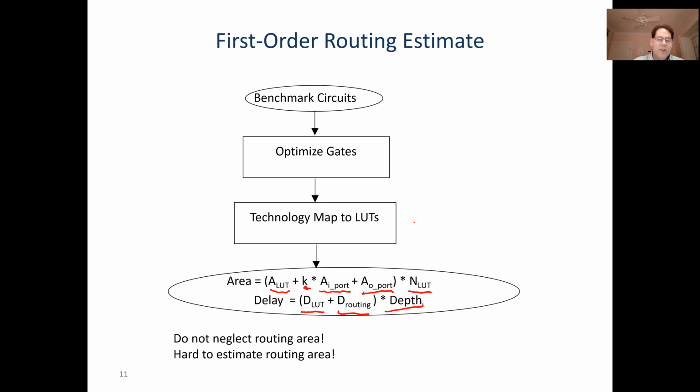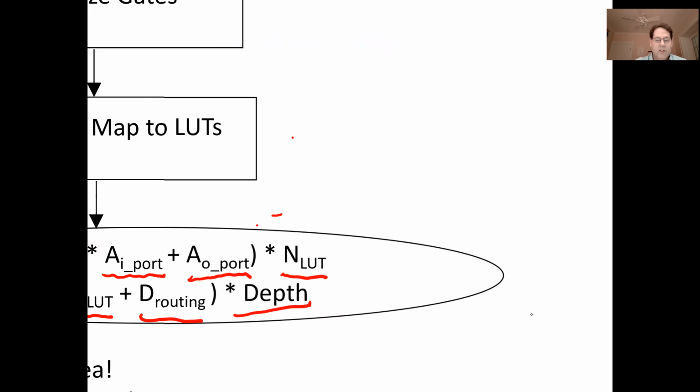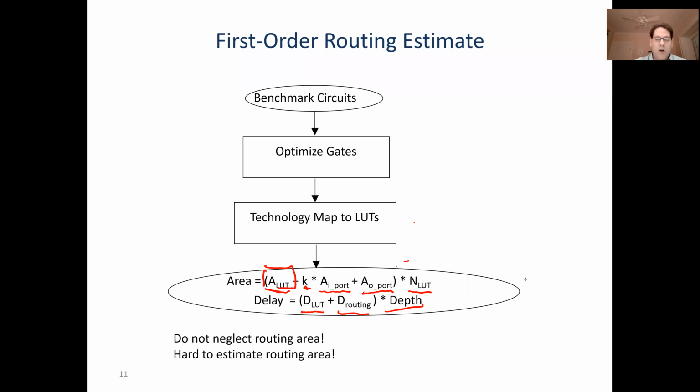That's interesting. I guess that's a good insight. Let's walk down that one. In this example, I'm doing just a logic block that's single lookup tables, so kind of simpler ones. The area of a LUT is going to be the area of the LUT I build. If I'm looking at a 6 LUT, it's the area of building a 6 LUT, whether I use it as a 6 LUT or not. The fact that I can't always fully utilize a 6 LUT shows up in this N LUT.